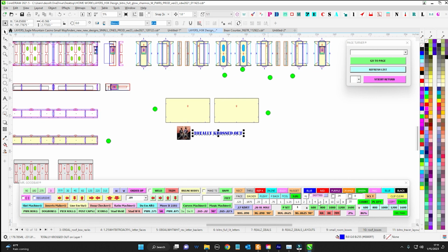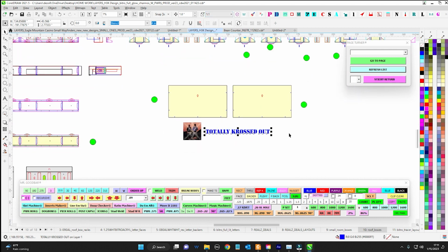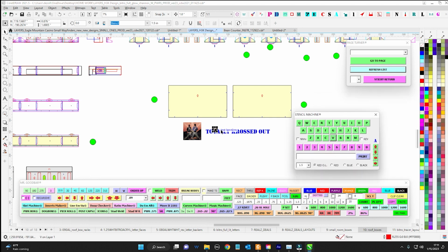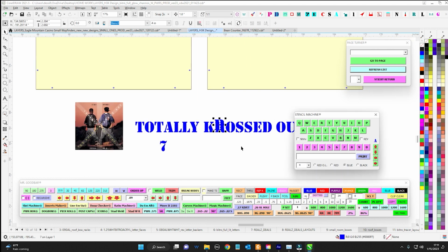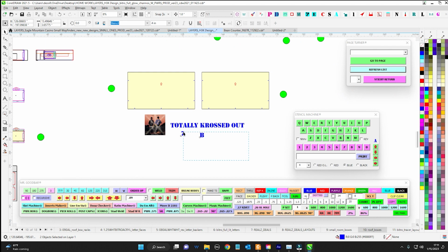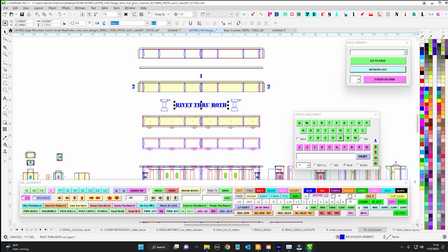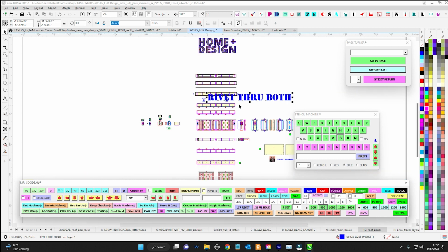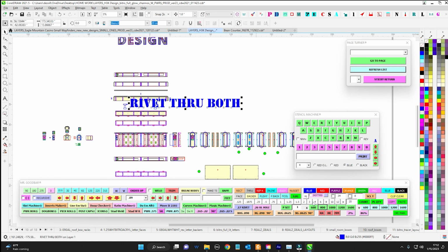So instead, I have these hot buttons, and because I work in 1-to-1, so an inch equals an inch, my default is around 4 inches. So when I type something, it's going to come out at a 4-inch tall height for those letters. And that works, but sometimes I do need to boost that size up quickly. So instead of going and trying to find it and change it and type it, I just hit these buttons, and these buttons will hot size to that inch size just that quickly. I think that was at 4.